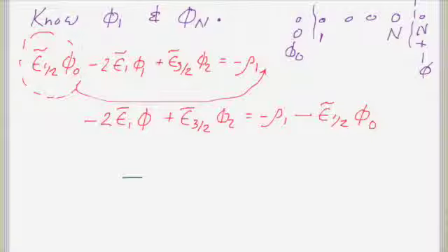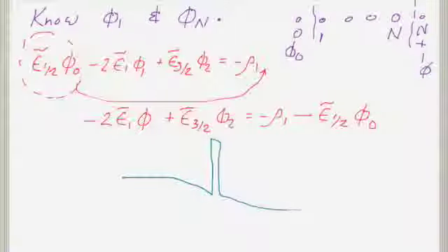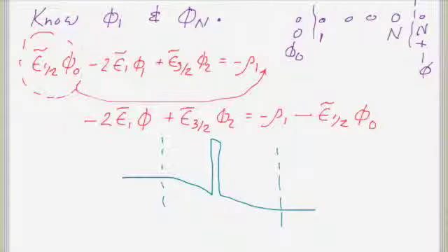So you've got some device in some region off on the left, where the electric fields have died down, and some region on the right. So over this entire region, say you're solving Poisson's equation, right? You're solving Poisson throughout all of this region where the electric fields are not zero, where the potential is varying as a function of position. And then over here, you've got some Fermi level on the left and some Fermi level on the right, mu left, mu right.